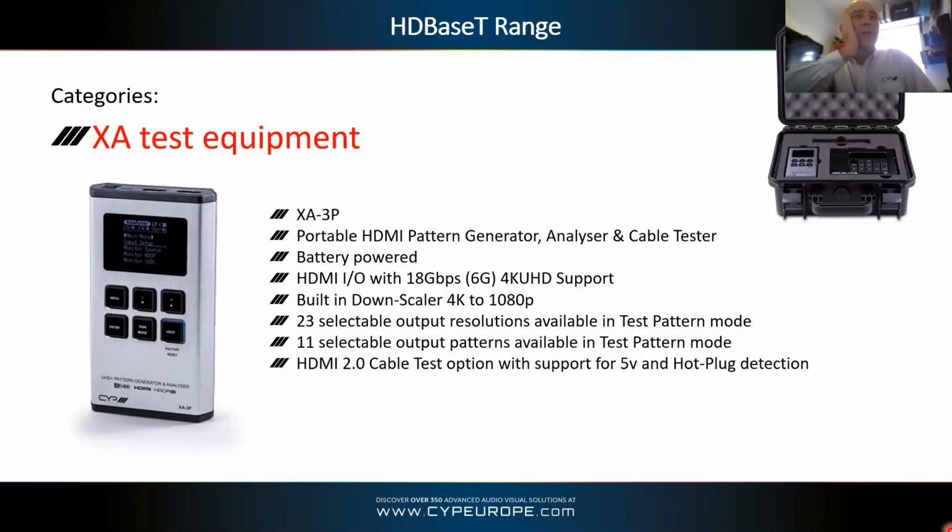The ability to monitor a signal at the end of your system before your TV's installed, so you know the system's there. The ability to act as a cable tester, the ability to push a pattern through a system to check your whole system's working, the ability to use it because it's portable at every stage of a system, trying to analyze if there's a breakdown in the signal. Is it this bit of cable? Is it that bit of cable? Well, if you analyze it at every bit, you can find out where the signal's breaking down. So really, I thoroughly recommend these. They're not very much money for what they do. You really should have one in your van.